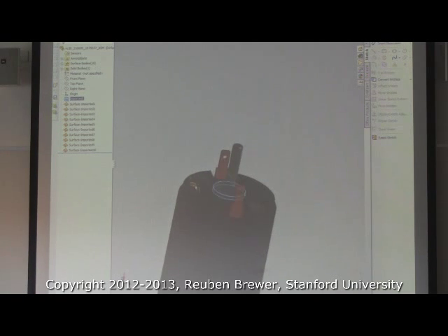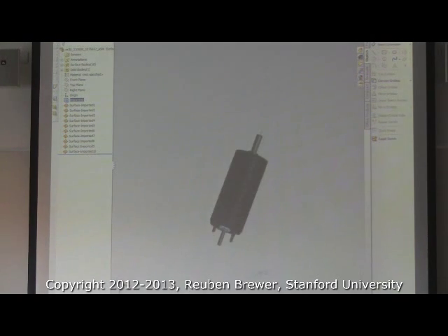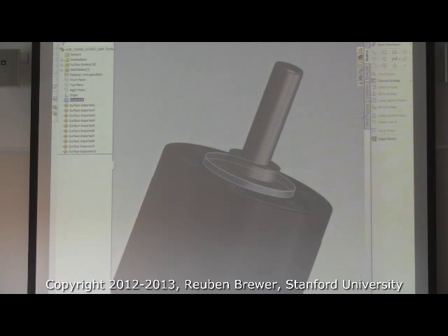Okay, so again, you can see this little hub here? That's what I use to center the adapter plate on. And then this one here. Anyone know what this is? So this is the centering hub. This is the shaft. What's this? No? That is typically some type of retaining ring to take out some of the axial play in the motor.